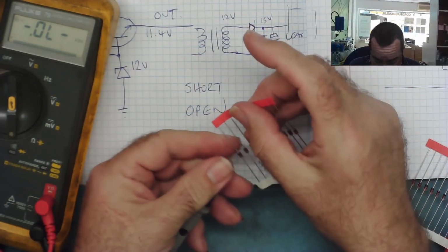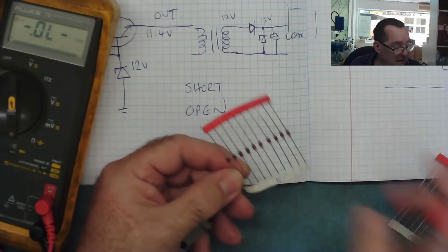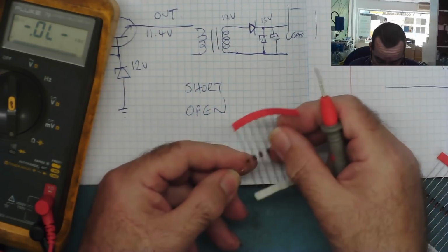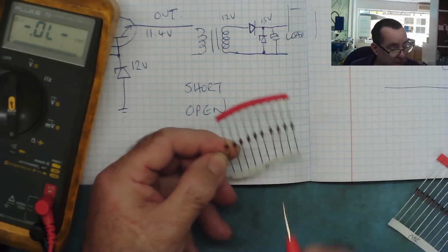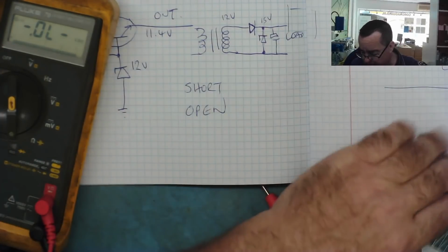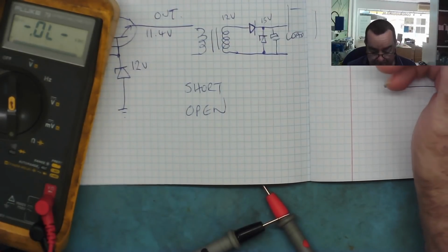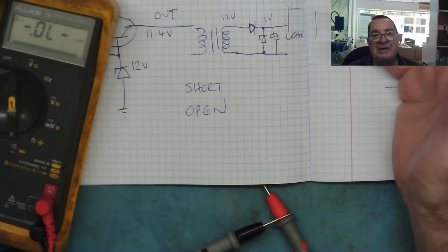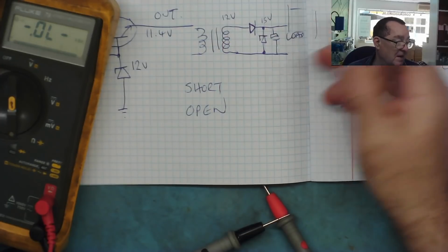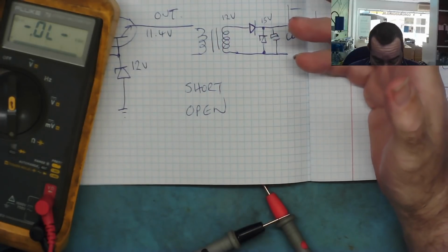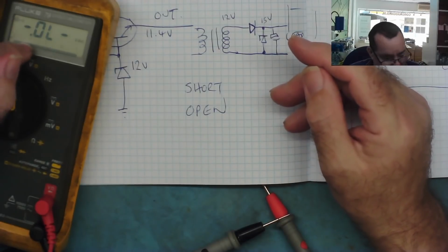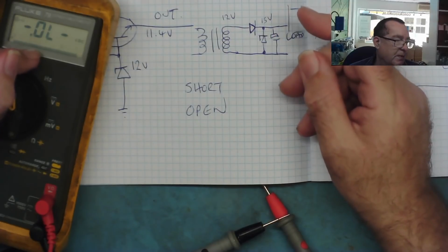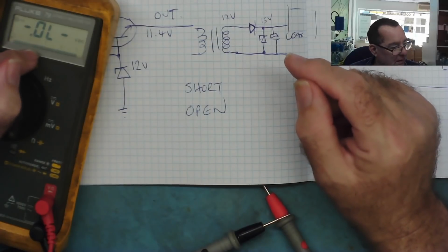Let's just go for another one. So this is actually an 18 volt Zener. In one direction it conducts 3.7, and the other direction it's open. So to your multimeter, a Zener diode will look just like a diode, and because they tend to fail in one of these two ways, pretty much so, yes, you can test the Zener diode in circuit quite often, and certainly out of circuit like that. But we can't measure a Zener diode with the multimeter if we don't know what the value is, or for some reason we do want to measure the Zener voltage, we have to do it a different way.